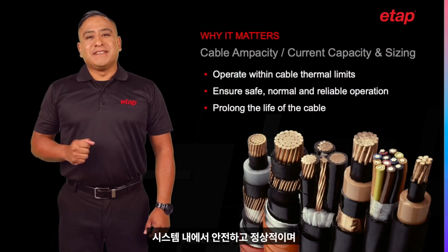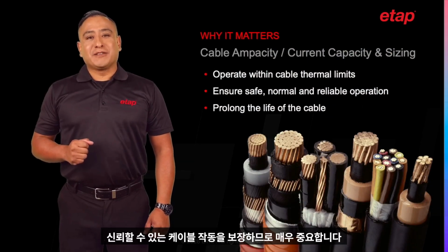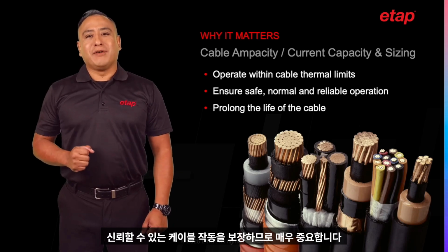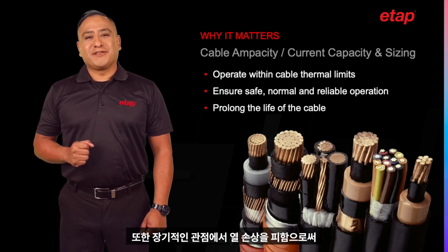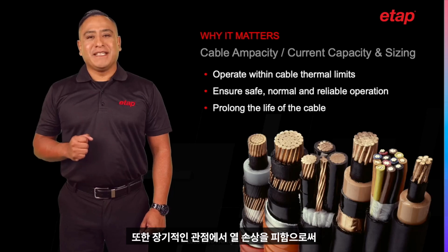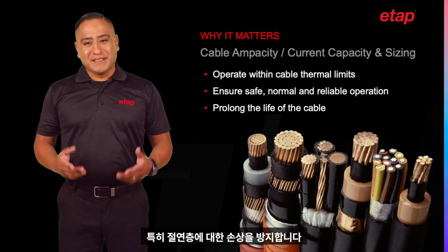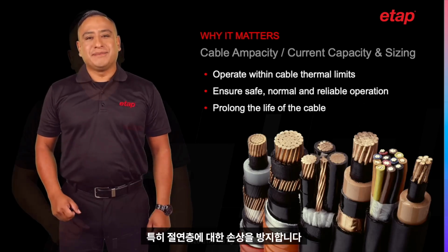Verifying that the cable does not exceed the thermal rating is crucial as it ensures safe, normal, and reliable cable operation within the system. In addition, from a long-term perspective, it helps prolong the integrity or life of the cable by avoiding thermal damage, specifically to the insulation layer.